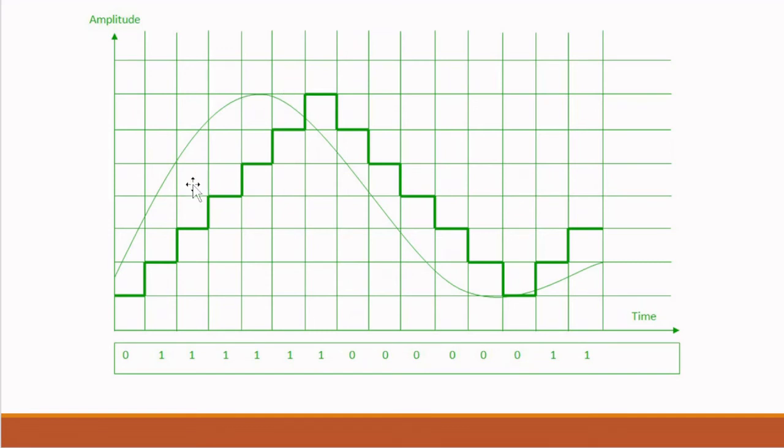Now we move further on like this. Here in the data set, the digital signal is higher than the analog signal. So now we go down the staircase. While going down the staircase, we decrease our value by 1. Comparing both the staircase values, since the previous state is higher and the current state is lower, we store 0 in our digital data set. And similarly, we follow this pattern for the whole analog graph.